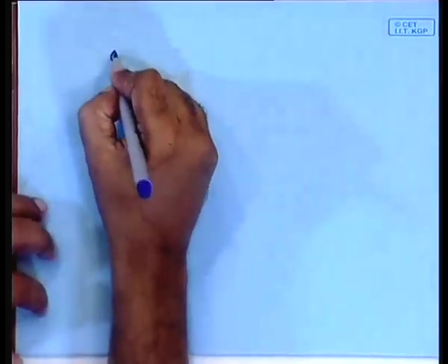What is the problem in choosing it too low, say 0.3, 0.4? No, you cannot do that, because the open circuit voltage is dependent on that. If you choose it low, the open circuit voltage goes down, and as a result the total power also goes down. So, there has to be some kind of a balance, some kind of a trade off, and it is now more or less agreed by people in the trade that the optimal band gap is something like 1.4 electron volts.